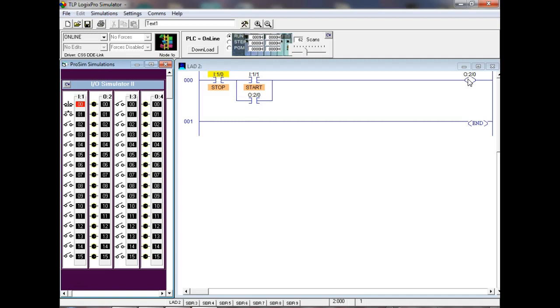Right? You understand? So notice that right now, this guy right here is not made because it's being controlled by what? By this guy right here. See that? So I'm going to come here and press that one. When I press it, the bottom one makes, and now I can release that button and it seals itself in because it's holding itself in.